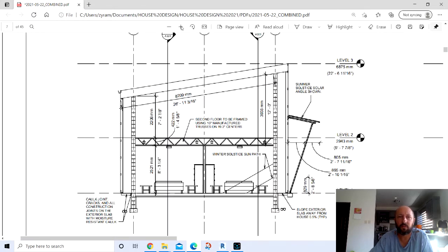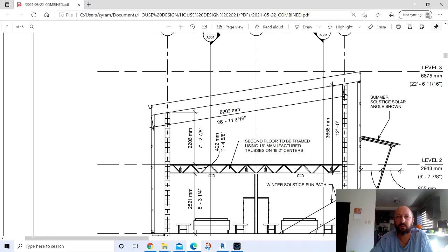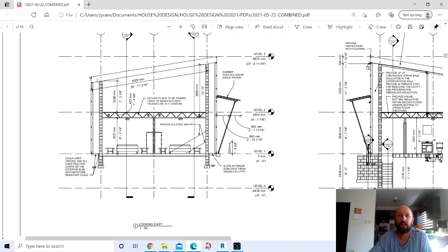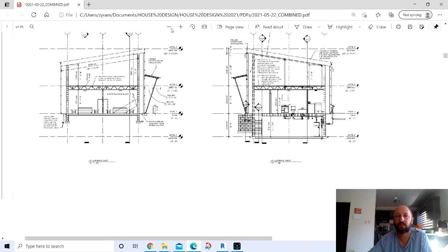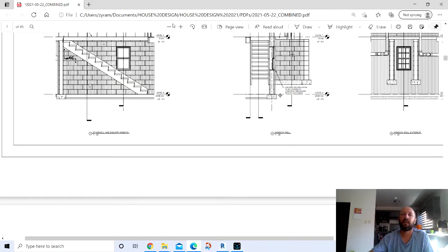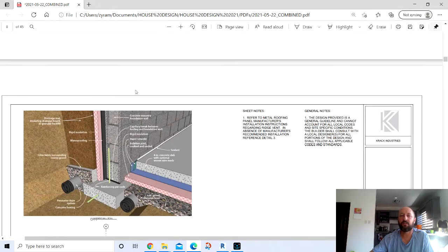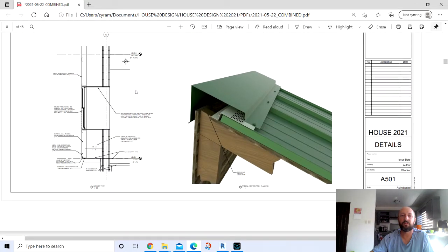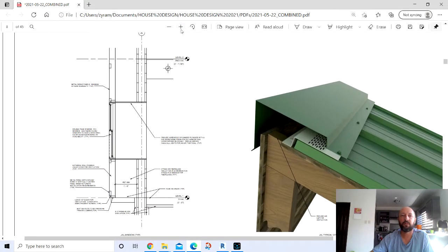The design incorporates a rain catchment system, so if all the water slopes to one side, then you just have all your downspouts on one side, and you have one pipe that goes through and collects all the water and takes it to your central cistern. And so it's easier to design your storm drainage system to collect all that water.